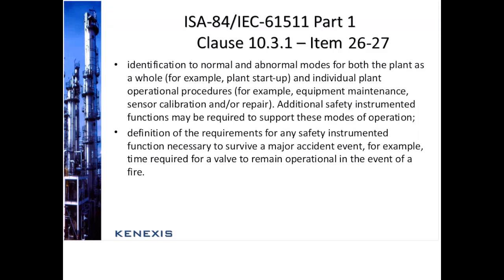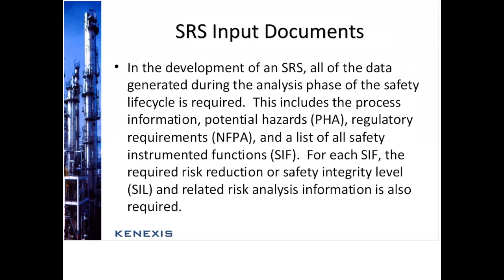Identification of normal and abnormal modes, and this is again talking about startup, shutdown, maintenance, calibration, repair. And lastly, the definition of the requirements for any safety instrumented functions that need to survive a major accident event. How long does a valve need to remain operational in the event of a fire? Things of this nature. So in the development of an SRS, all of the data generated during the analysis phase of the safety life cycle is required.